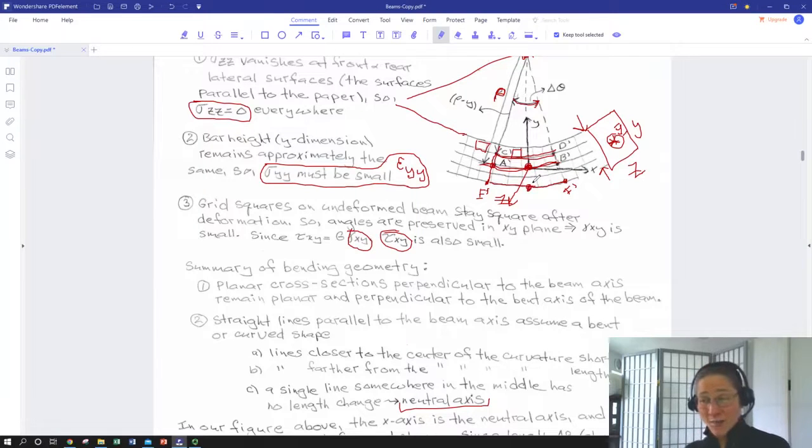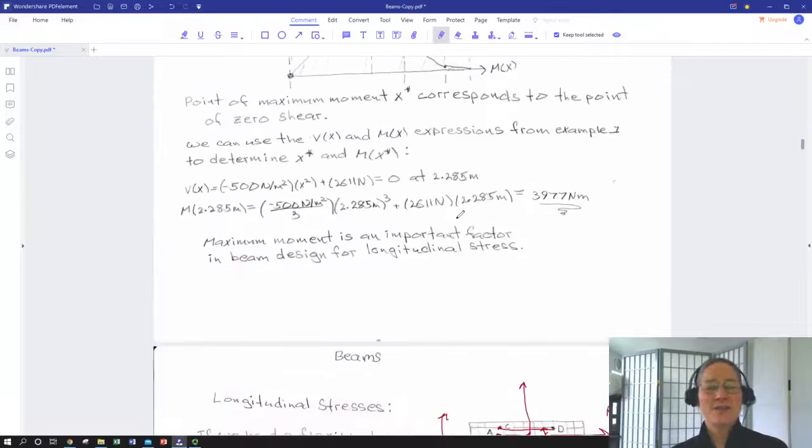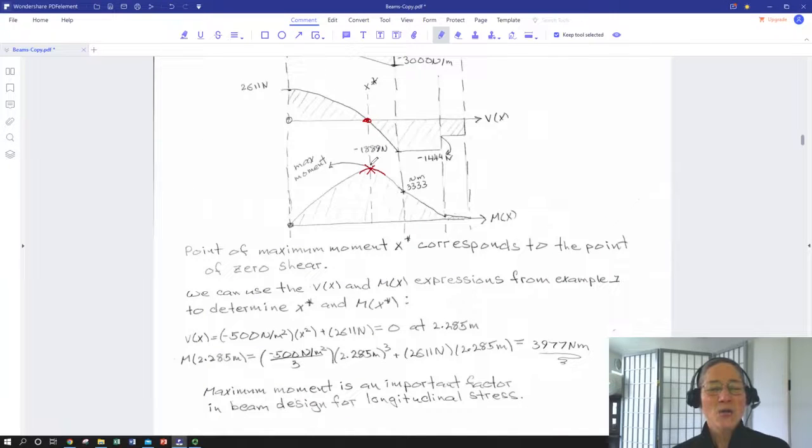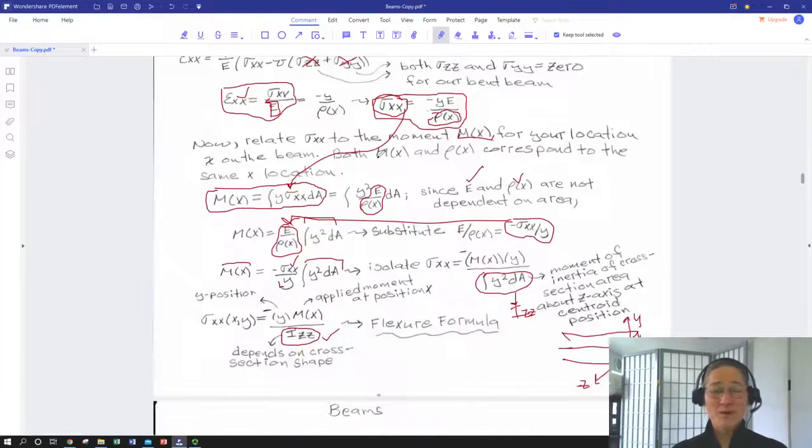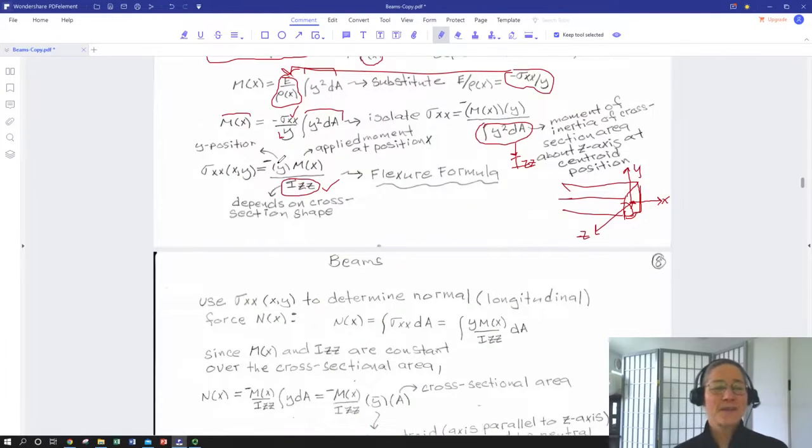at a point along the beam, and I'm going to go back to material from a previous lecture, where maybe the internal moment m as a function of x is a maximum, and maybe we've picked a beam with a very small moment of inertia, a small IZZ. This might get pretty big. Furthermore, this negative sign says as we travel from the neutral axis towards the center of curvature and we're contracting, we have compressive stresses. No worries for most materials.